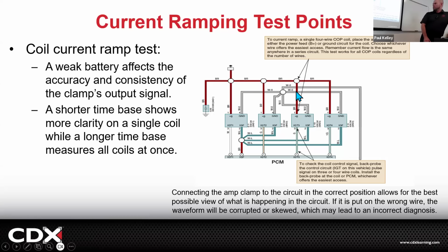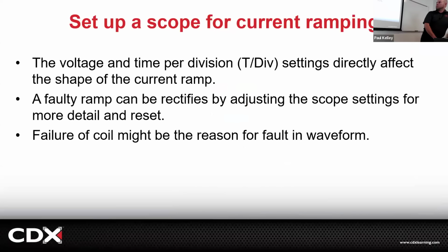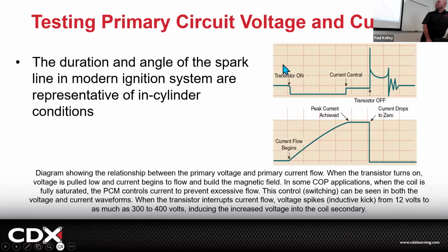Cool? But then let's just say we wanted to measure the ignition coil trigger, which would be in voltage. We'd actually use this one, which is IGT. That's the trigger. That's going to more be the waveform. So sometimes we're measuring the current ramp on the positive, and generally we're measuring the trigger on the negative, right? So if we were to look back at these, that would be on the positive as an amp. This would be on the negative as a volt. Okay, makes sense?